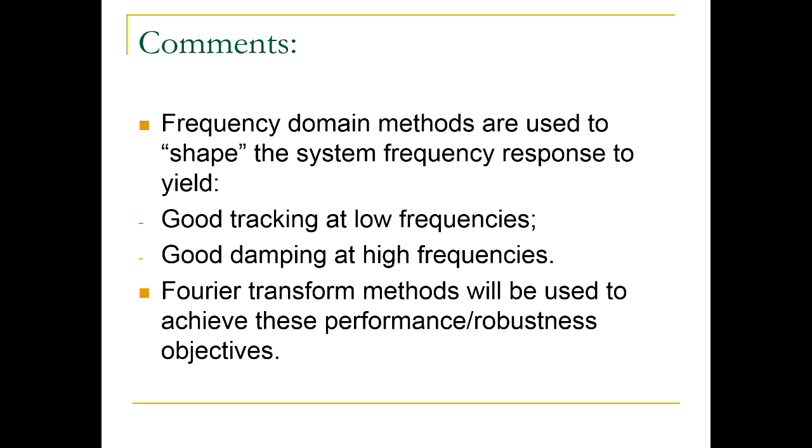All right. So frequency domain methods will be used to shape the system frequency response to yield good tracking at low frequencies, which is basically reference signals, and then good damping at high frequencies, which is basically suppressing the noise. So then frequency response methods, I shouldn't say Fourier, will be used to achieve this robust performance. We will learn about these a bit later.